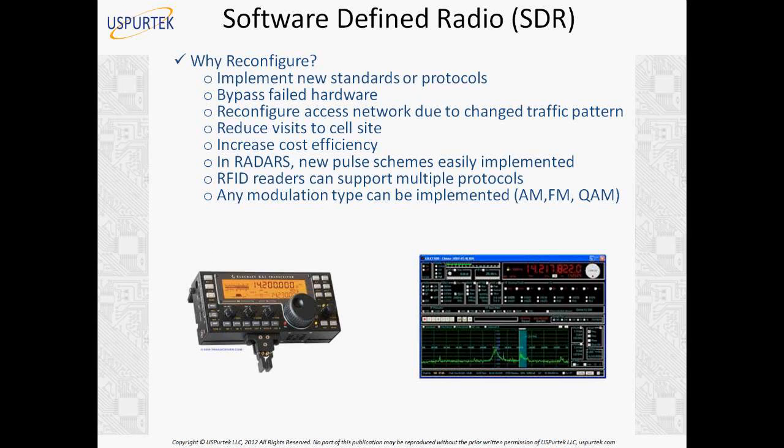For radar applications, you could implement new pulse schemes which are easily implemented. Instead of designing everything in hardware, you can just change the algorithm in software to implement a new pulse scheme. RFID readers, if they are based on SDR, can support multiple protocols. So any modulation type can be implemented, not just QAM. You can implement AM and FM also. So definitely SDR gives us more flexibility, and that is a goal.